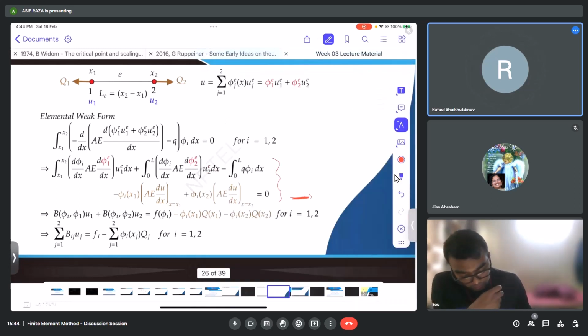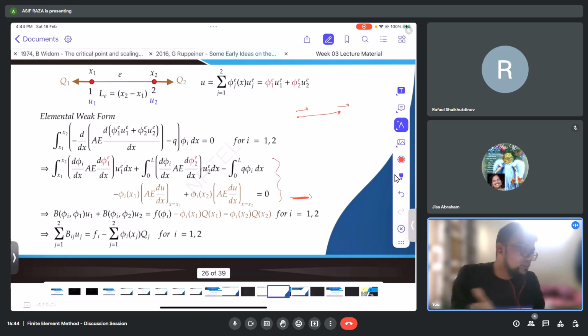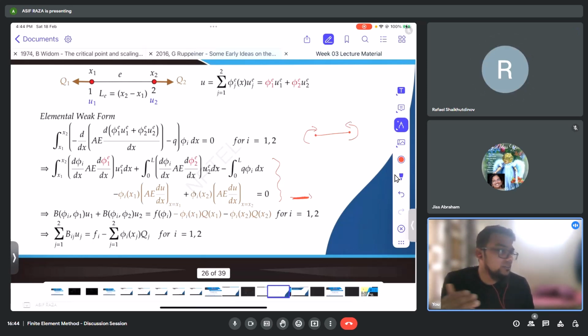So for the finite element method, what we do is assume a particular sign convention, like u1 is along this direction, and it will be the same direction throughout the element. In strength of material, if I remember correctly, for sagging moment we take a positive sign when, from the left hand side it's clockwise, and from the right hand side it's counterclockwise.